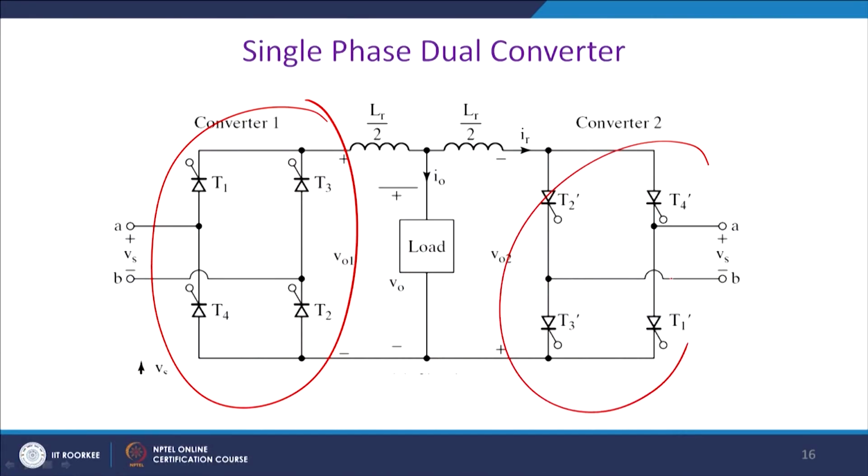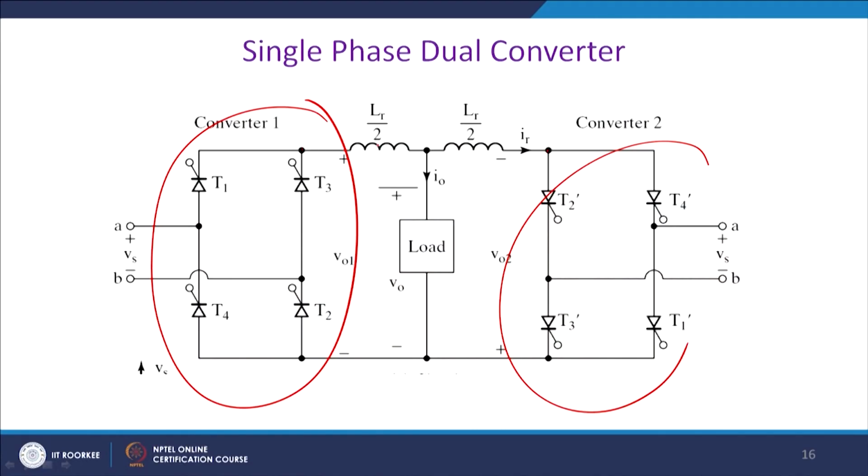Same way, but you see that the polarity of these thyristors is reversed. So, for this reason it will be minus alpha, and since the pole voltages may have an instantaneous difference, you require a current blocking inductor, so that it can block the instantaneous voltage between these two pole voltages.